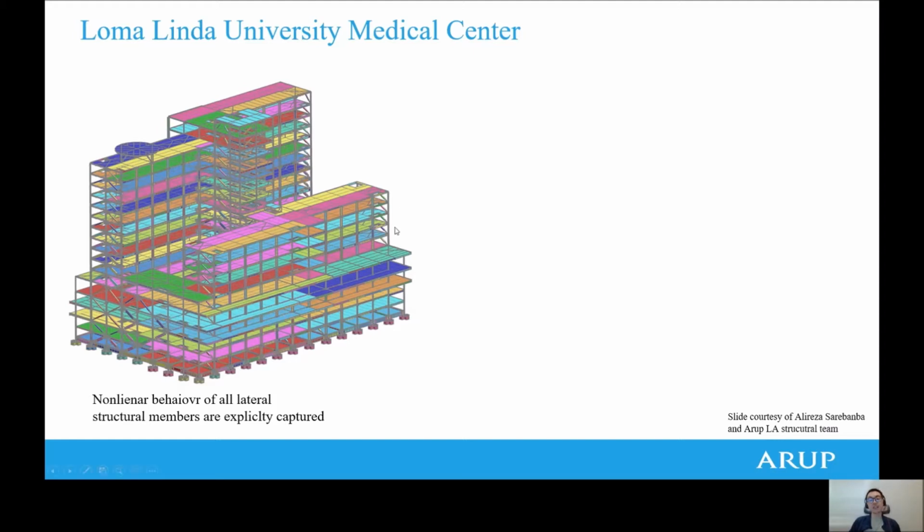For the horizontal isolator, we use the advanced isolator-type material in LS-DYNA, which has the most advanced features for modeling triple friction pendulum isolators, including the failure of the rim and their large horizontal displacement. The dampers are simulated with damper elements with displacement lockup modeled.